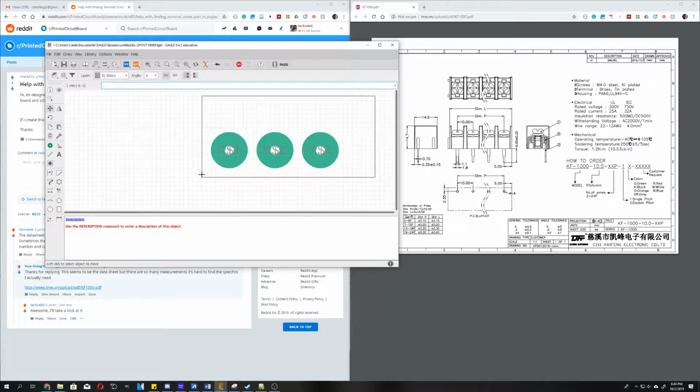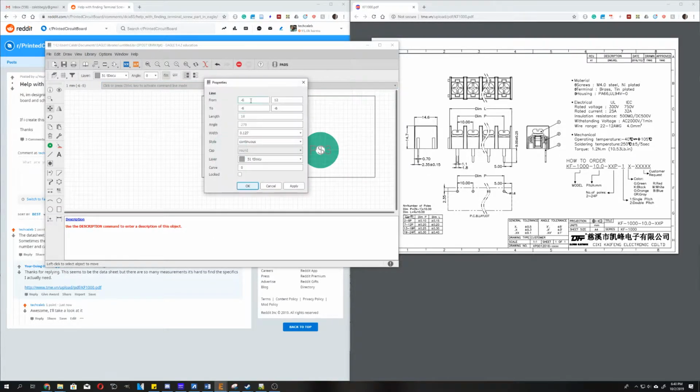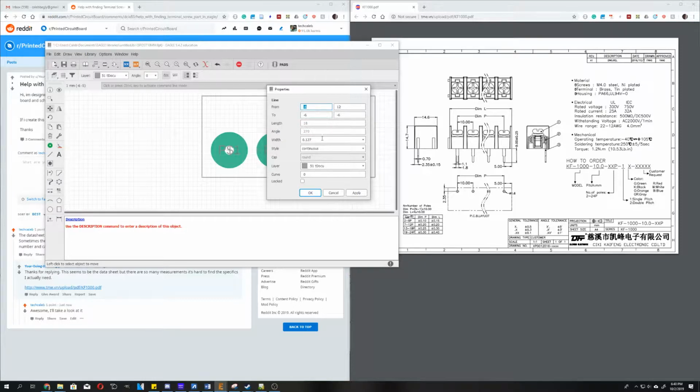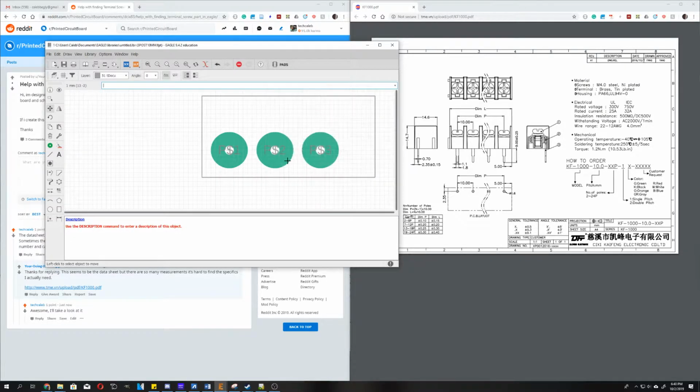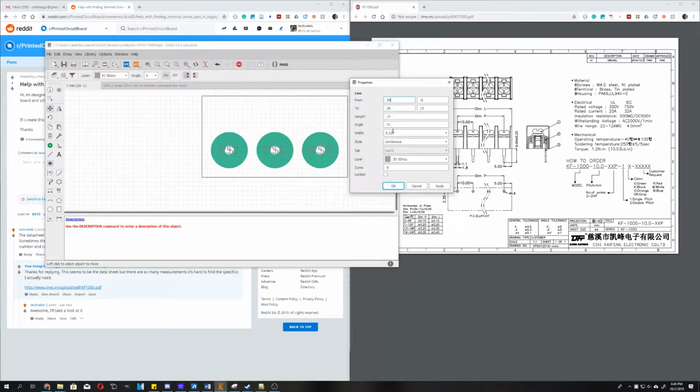So you could count over and figure that out, or you can go directly into properties and you can actually type it in. So we actually drew it correctly the first time. That's actually 6 millimeters over there. And then as far as where this other side here is, again, you could count over, you could basically eyeball it because you know it's 2 off of the side there, 2 off of the side there, because that's a radius of 4. Or you could say from here, we know it's 10, 20, and an additional 6, so 26. And there it is there. So these are XY coordinates.